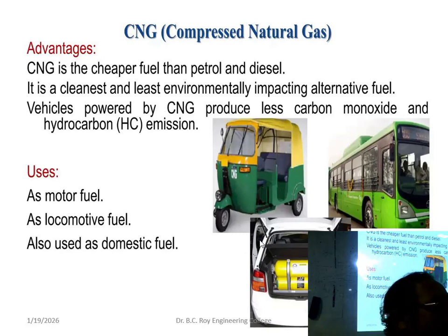That is a major disadvantage of using this fuel, because you always have to keep the CNG kit in the backside boot. Otherwise it's not possible, because you don't have space on the front side. All the cylinders, whether 1 cylinder or 2 cylinders, you have to keep here. So this space is already occupied and you cannot keep luggage here. There is another disadvantage: 30 to 40,000 cost for the CNG kit. People are using it sometimes.